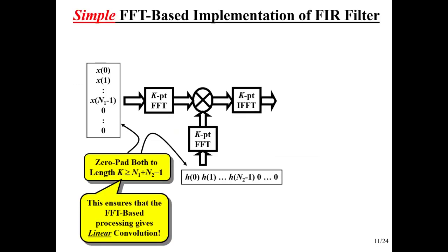So here is a simple FFT-based implementation of an FIR filter. So notice I'm stressing simple. We'll see that this solves some problems and is applicable in some scenarios, but creates other problems for our scenario. So here I am zero padding both the signal and the filter out to some length k that satisfies that.